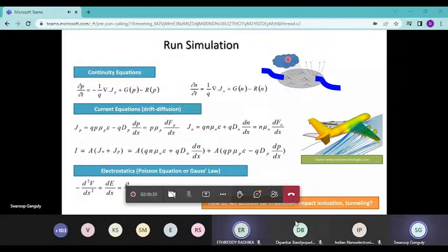It can change because you have some water being added. That's generation of new water. And you can lose water by evaporation. So there are these three things that can go on. And you see those three things exactly here. The density of electrons changes because there is a change in the current density, which is the flow through this river. Generation of carriers, which is this rainfall here, and recombination of electrons and holes, which is analogous to water leaving this reservoir by evaporation, recombining with the cloud. So this is the continuity equation. And the point of this analogy is that it's very much like fluid flow.